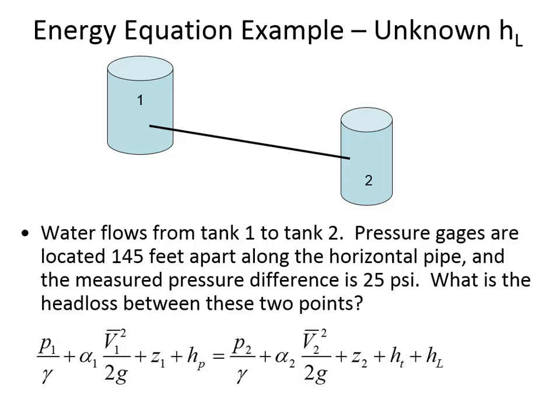And sometimes that's a hard concept to grasp, that if it's losing energy, it seems like the flow would be slowing down. But what we know mentally is that since it's in an enclosed pipe, it can't slow down because the water behind it is pushing it forward. There'd be no place for it to go if it was slowing down. A pipe can't allow accumulation of flow. And so the flow continues at the same rate in the entire pipe, even though pressure is decreasing. The energy loss is manifest in the pressure decrease, not in a reduction in velocity.